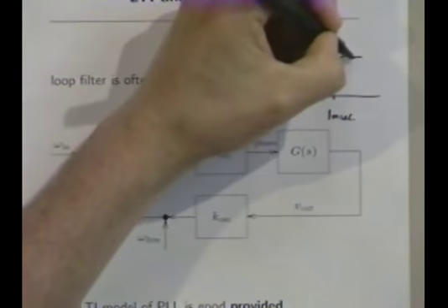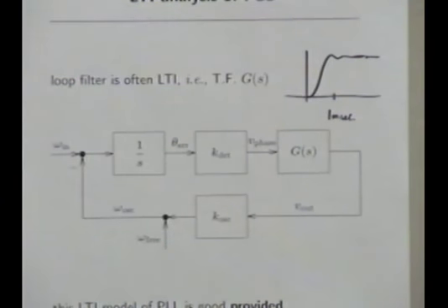And when it's up here, that means it's tracking again. Okay, so that's what that means. That's what the step response means. It tells you how fast this thing can react to a rapid step in frequency and readjust its own oscillator to, again, phase lock. That's what it depends on.